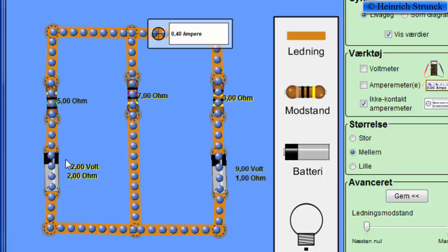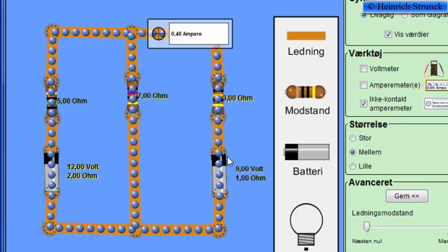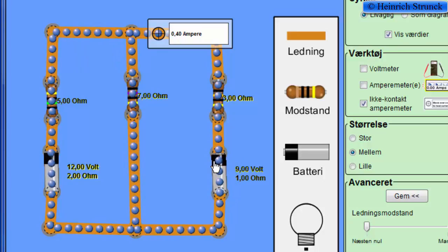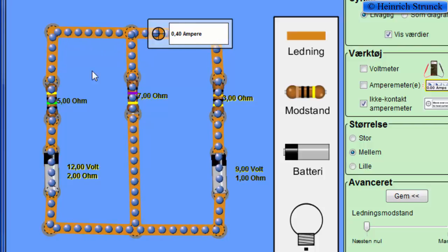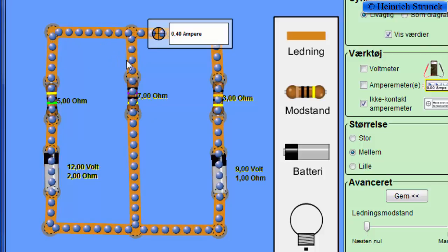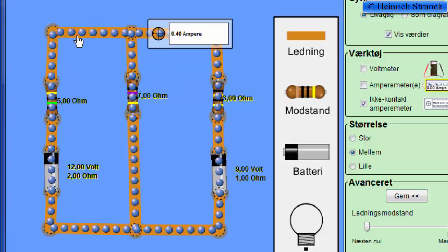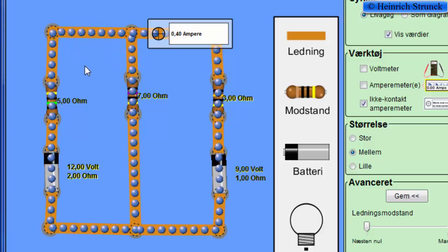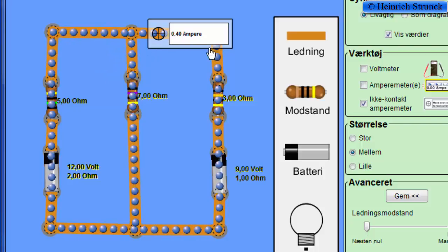Then we take out this voltage, 12 volts, and then it is only the 9 volts which leads to the current in the system, and we then calculate the 3 currents again. And finally we add the 2 currents for current number 1, and that is the correct current, and also for number 2 and number 3.